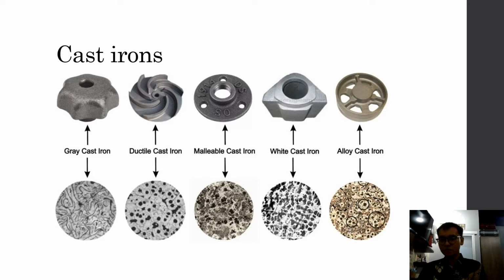However, gray cast iron also has important advantages. It is a low melting alloy, having high fluidity at casting temperatures and low shrinkage, which makes it well suited for casting into complex shapes. It can withstand higher temperatures better than steels without warping or oxidizing, and is therefore used for doors and furnace parts.